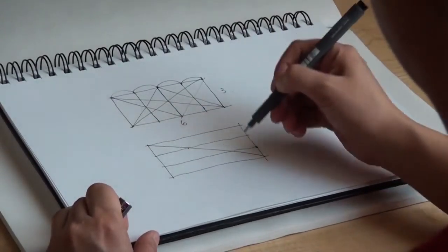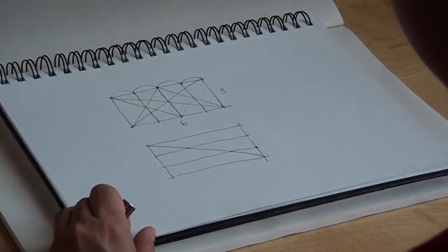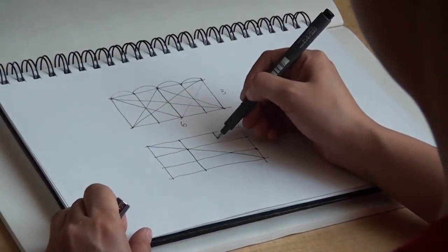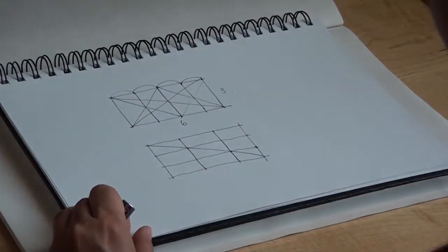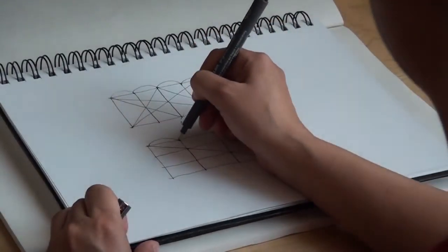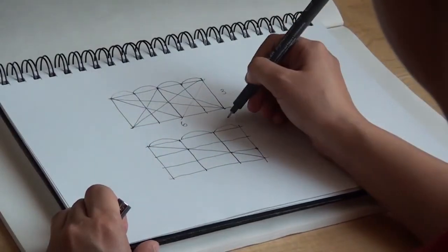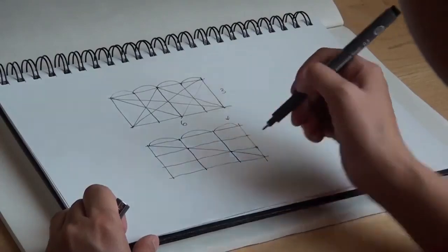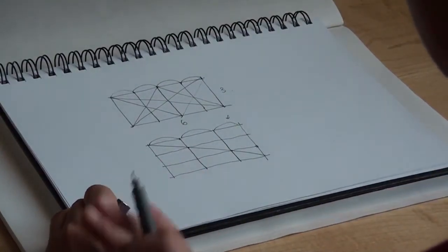When the diagonal line crosses your horizontal line, you can go through them and draw a vertical line. So if you did the work perfectly, they should be equal parts. This is a little smaller because I wasn't dividing this line perfectly. So that's how you divide.